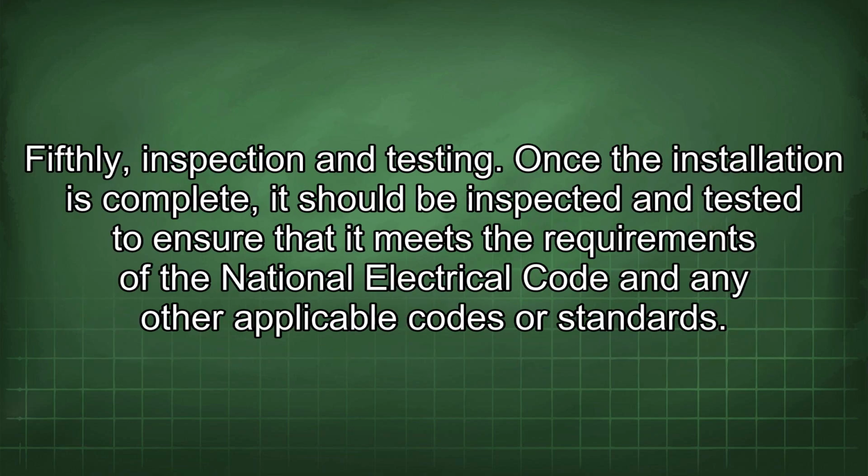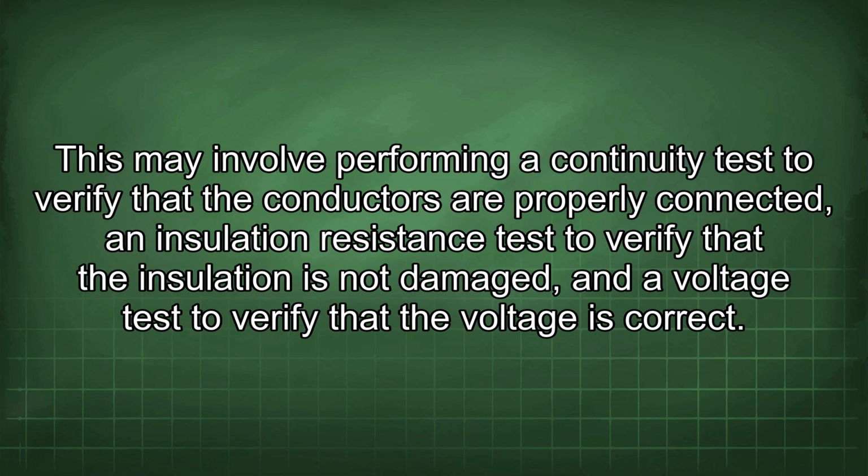Fifthly, inspection and testing. Once the installation is complete, it should be inspected and tested to ensure that it meets the requirements of the National Electrical Code and any other applicable codes or standards. This may involve performing a continuity test to verify that the conductors are properly connected, an insulation resistance test to verify that the insulation is not damaged, and a voltage test to verify that the voltage is correct.